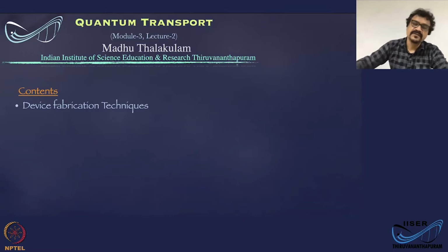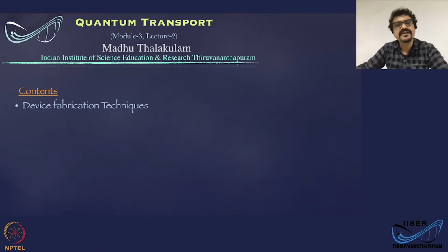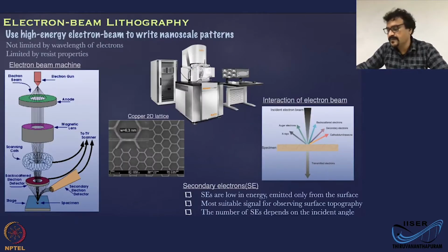In this lecture, we'll overview the electron beam lithography technique. In the previous lecture, we went through the photolithography technique and its limits. Photolithography resolution is mostly limited by the diffraction of the UV light or UV radiation. In the contact mode or soft contact mode, it is limited by the near field diffraction, and in the projection mode, it is limited by the far field diffraction.